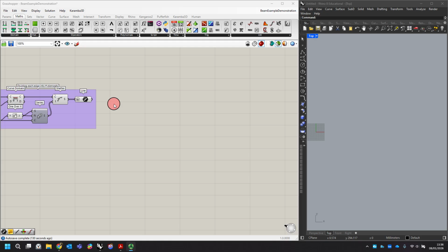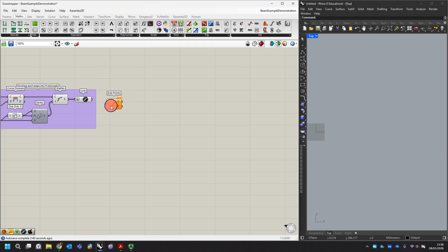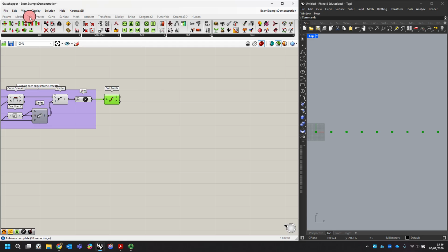So to start that process, we can just type endpoints. So that gives me the start and the end point for each line, like so. Just tidy things up a little bit. And what I'm going to do is, this is a little bit of a cheat. So from the sets, I could actually construct a complete set, but I happen to know that if I take a set union, that will actually return a set of unique values anyway. So it's just a very slight shortcut.